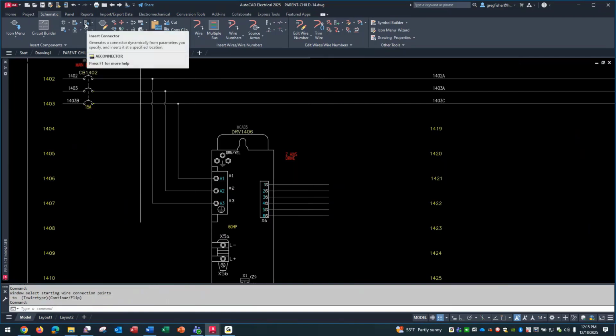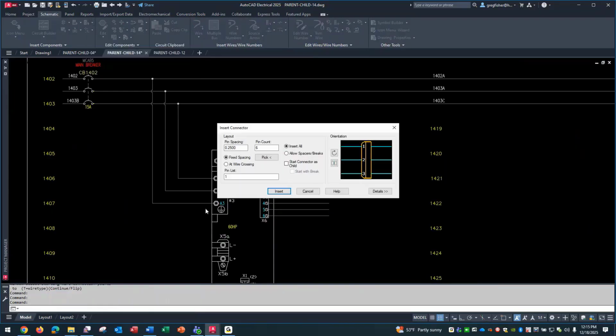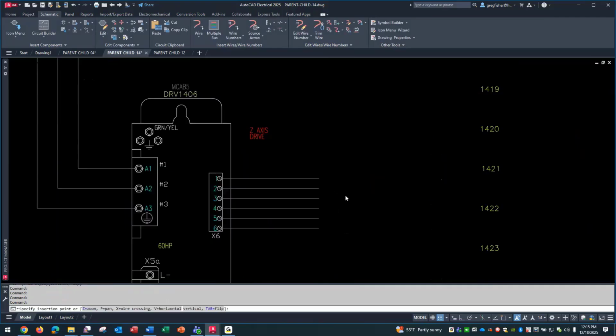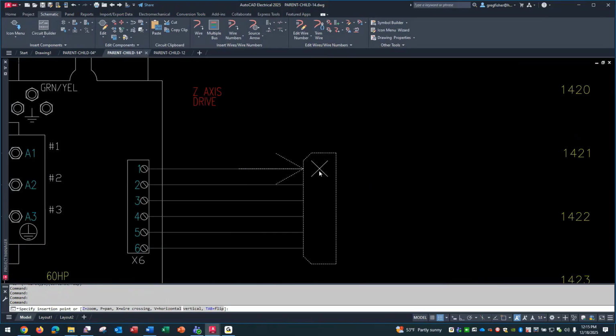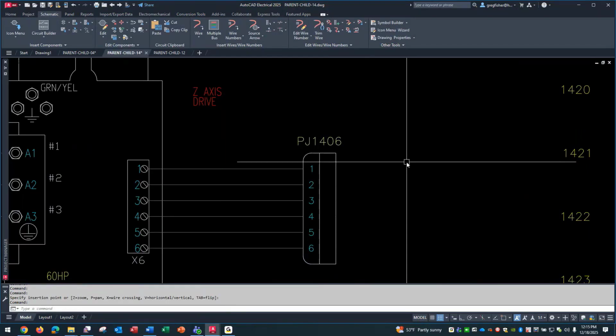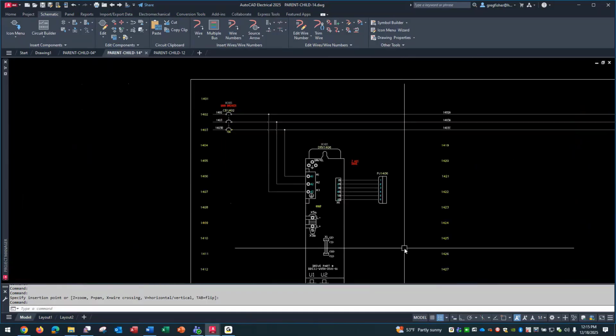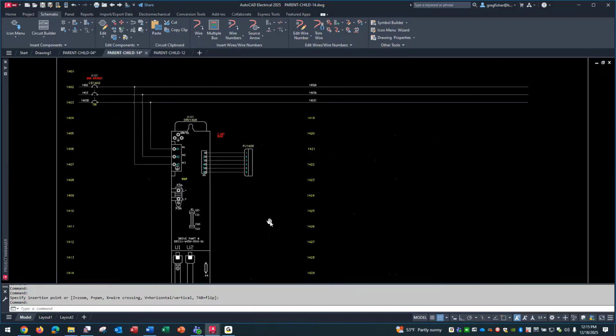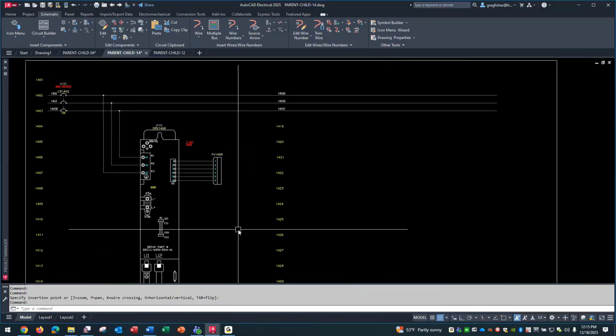And then maybe that particular connector was going to another connector. So I'll just insert, just as an example on how it might get wired up. And typically I'd fill information in here just to save time. We're not going to. So that would be an example of just your basic parent symbol. No child symbols are going to be linked to it. You're going to show all the wiring in one drawing. And that's not uncommon. I'm not telling anybody not to do it that way.